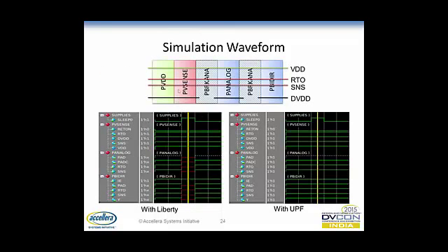I have given an example here where there is a power management cell, then there is a section of the ring in between, which is analog, and then again a power bidirectional cell. The bidirectional cell and the power control cell, which is PV sense, are operating in the same voltage domain, whereas there's an analog cell sitting in between. Now what will happen if the analog power domain is down? It will corrupt the control signal unless you define those control signals as feed through and floating.